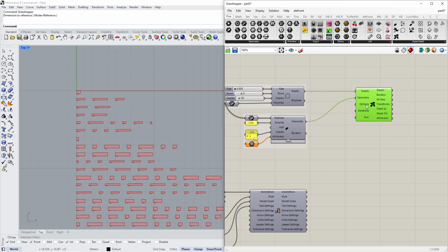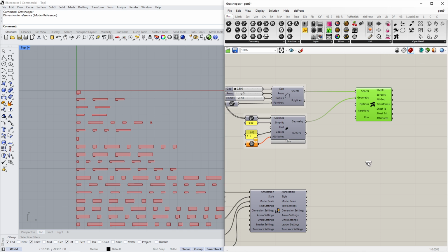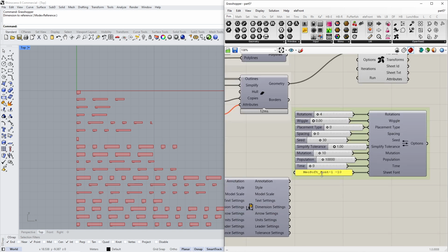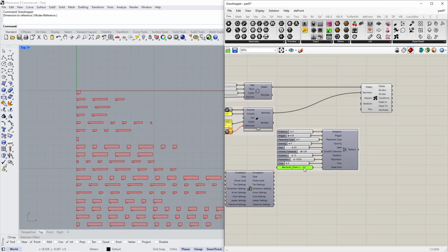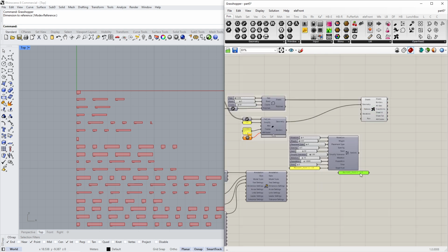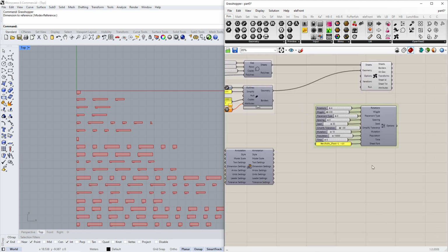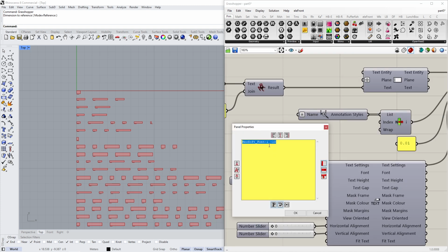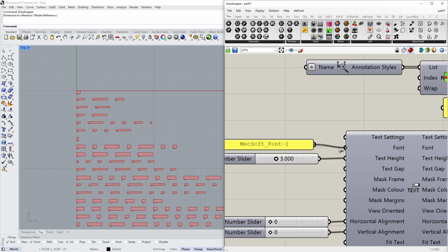Because for the nesting component, there's an options input. And if you insert that options component, it directly comes with some inputs as well, and also the sheet font. And this font, the Maxsoft, is a single line font. So we're going to use this one for the font here. Because I always forget the name, but this way you can just copy this panel. So you have the font here. I would just remove the -10 in the end, because we're going to specify the height ourselves.